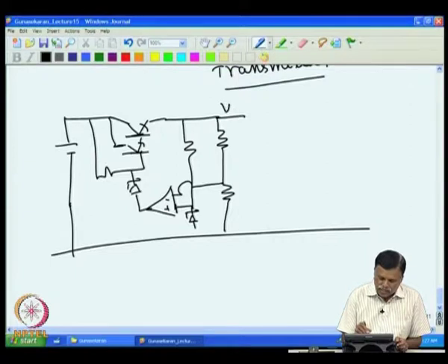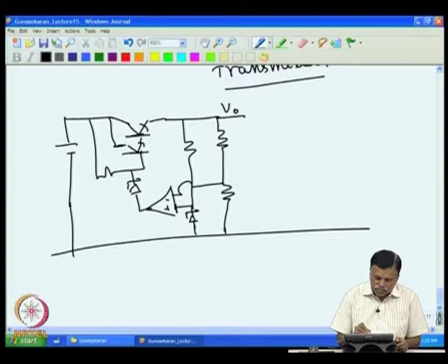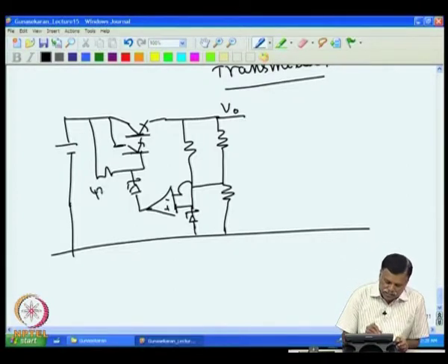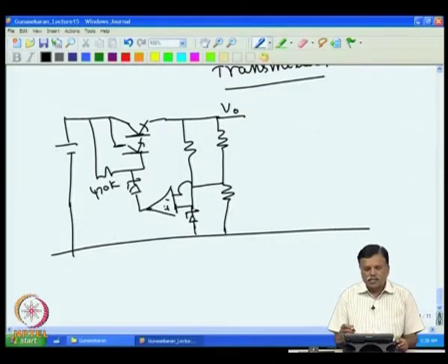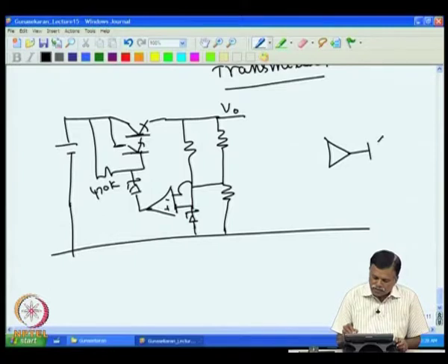So, this is the voltage regulator part of the current transmitter. We had a 470 K resistance here, in order to give a startup current. Now, then we draw the other part of the circuit, that is the transmitter part, like this.